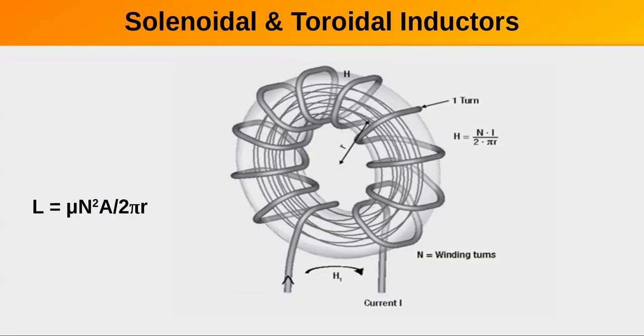Which is why I think that is a factor in trying to figure out why, if you increase the size of the conductor, it affects its electrical length. Because if you look at that formula and you look at the formula for capacitance, where due to skin effect you've only got the outside of the conductor, it appears that increases at a higher rate than the inductance does.